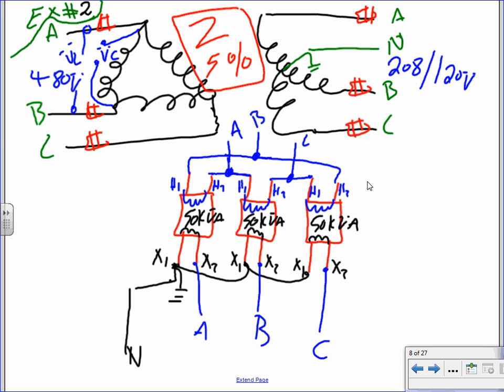By the way, all the steps are identical, almost. So 3 single-phase transformers. Each one of them is 50, 50, 50. They are hooked up on the primary side as a delta. On the secondary side, they are hooked up as a Y. Can you guys see the connections? There are 3 phase on the secondary, plus a neutral. On the primary, there are only 3 phase, no neutral. Can you guys see that? The impedance of that baby is 5%.